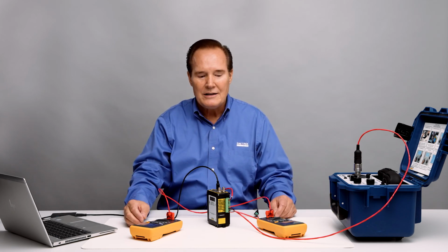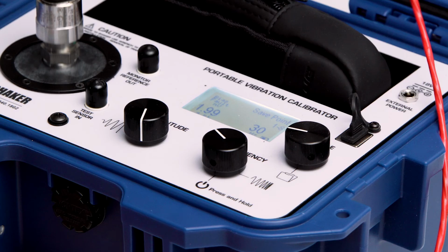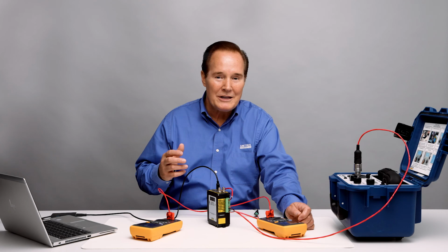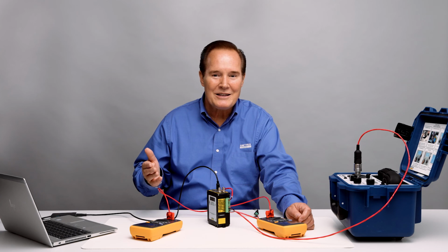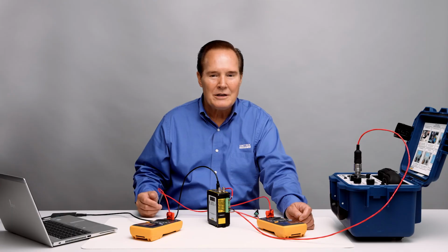and so what you see on the meter is 16 milliamps. Okay, and what you see over here to the left is that since the shaker is reading 2 Gs, 2 Gs is 20% of full scale. So 16 milliamps times 0.2 is 3.2, plus 4 is 7.2 milliamps. And we're at 7.0, so it's very close. It's well within a few percentage points. 10% is 1.6 milliamps, 5% is 0.8 milliamps, 4% is 0.4 milliamps. So it's within 0.4 milliamps, so it's down less than 5%. So that's very good. It's half of that, 2.5%.